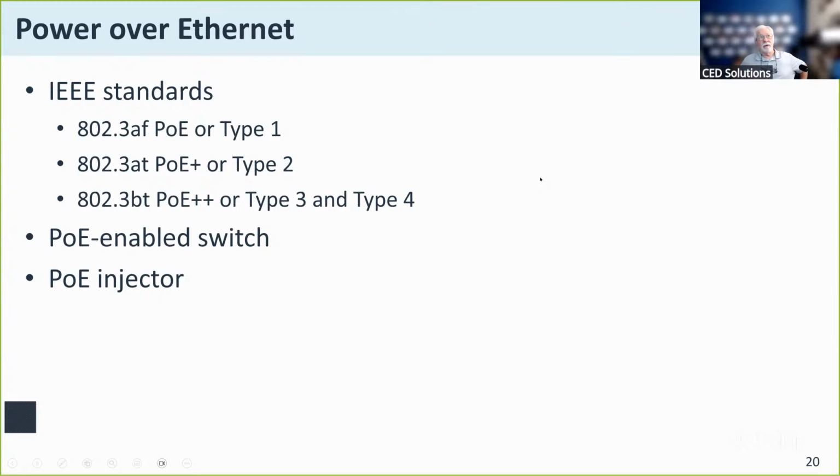This power over Ethernet standard, or standards, provide the ability so that you don't have to run an additional power cable from the switch device out to the camera itself. The power can be sent right down the 8-wire twisted pair Ethernet cable. And I mean heavy duty power too. Some of them, they're experimenting now with up to 70, 75 watts of power right down that same network cable. So you don't have to run additional power cables.